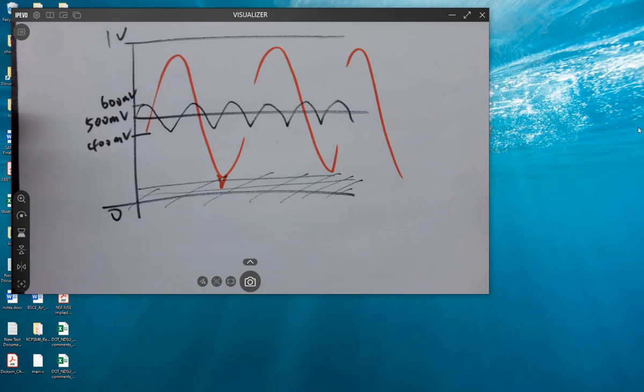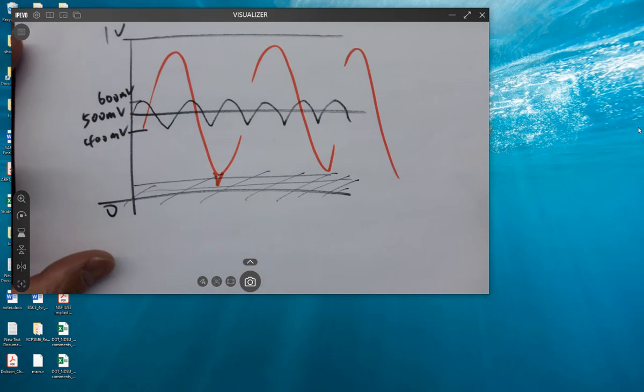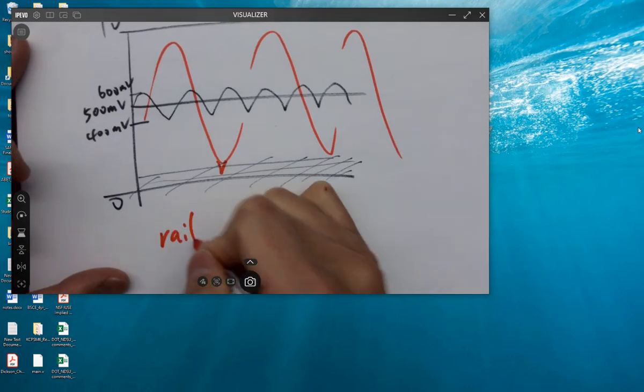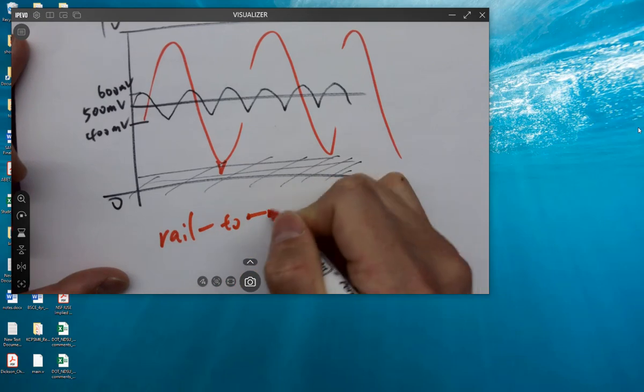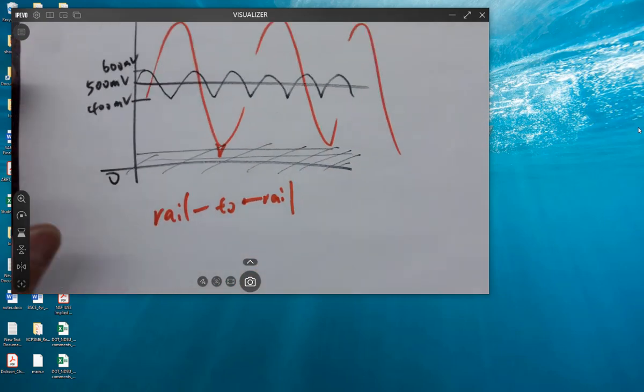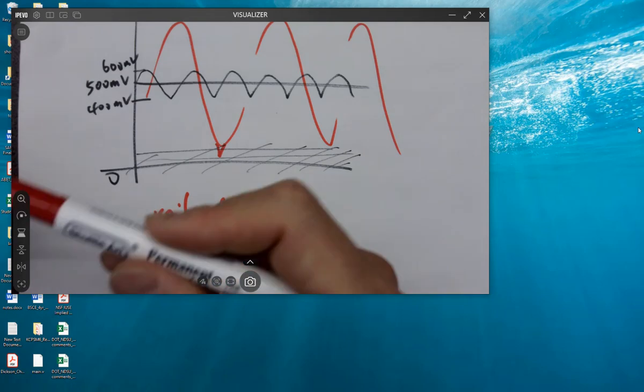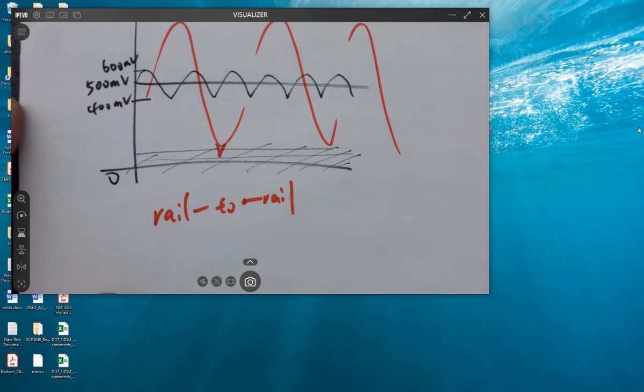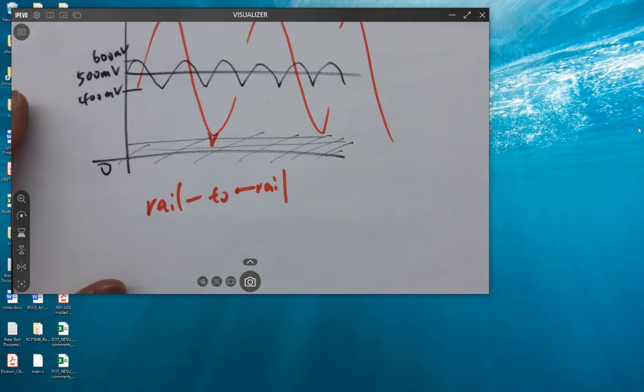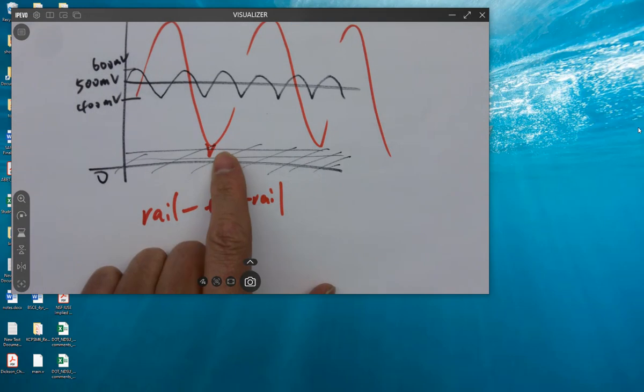However, if you replace that comparator with the rail-to-rail swing, you may get a better performance. So this is part of the project. I'm gonna work on it as well and see if I can make it. Otherwise, I'll let you guys try it, explore this a little bit. But this op-amp provided by the textbook already works. It's just not perfect because the low voltage range is having a lot of errors. It's not rail-to-rail swing.